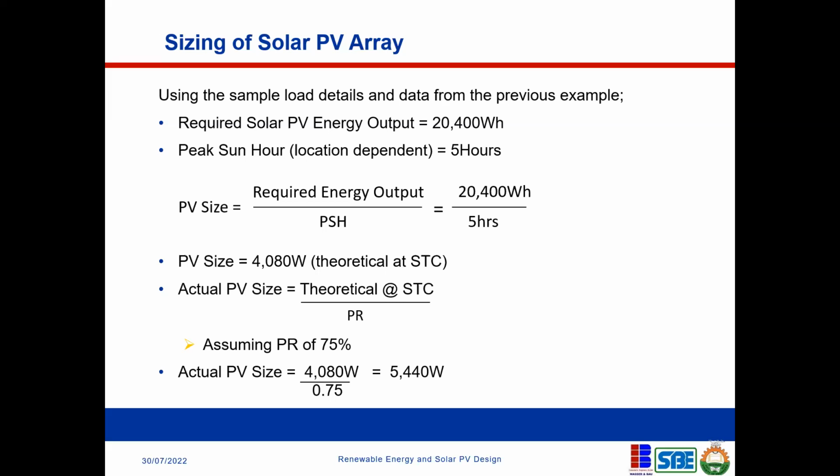Does aging affect the performance ratio of a PV system? Of course, yes. All this while we have been talking about the natural stuff, the physical environment, temperature, etc. Then how does aging affect the performance ratio of a PV system? Some of these details are provided in the PV model documentation by the manufacturer. For some PV systems, every year they have about a 0.5% degradation.